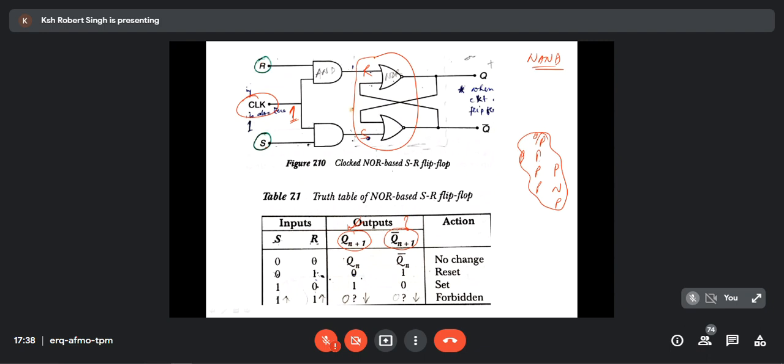By the nomenclature, n plus 1 means one stays ahead. N means previous. So previous, present, next state or present state. Do you get confused by what I say? There is no confusion. In whatever manner you want to think, you can think. In some books, instead of Qn, they will write Qn minus 1. So they think of Qn as the present and Qn minus 1 as the previous. That also is good. The only thing is that there should be a difference.